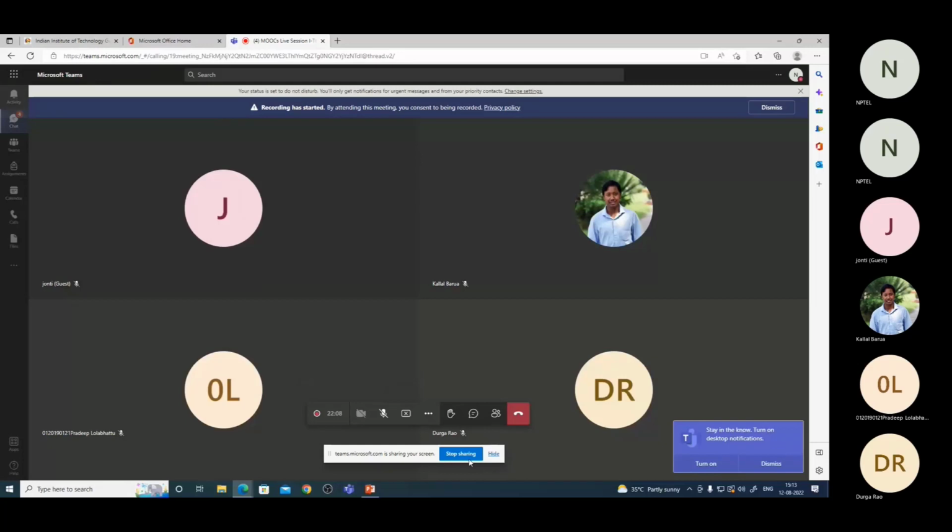Then it was asked to find the heating time in minutes needed to obtain a probability of spoilage of 1 upon 100. That means one survivor for 100 microorganisms. So it is nothing but the final microbial count, which you can take as 10 to the power of minus 2.